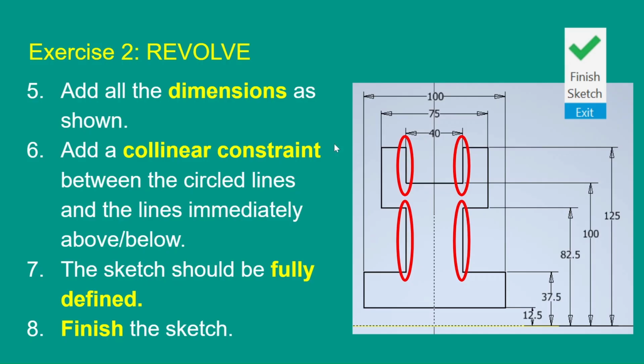Now if you use center lines, if you change this to a center line, I didn't show that, but when you put in these dimensions, they're going to need to be double of what's shown here. I just use the construction line instead of that center line option.